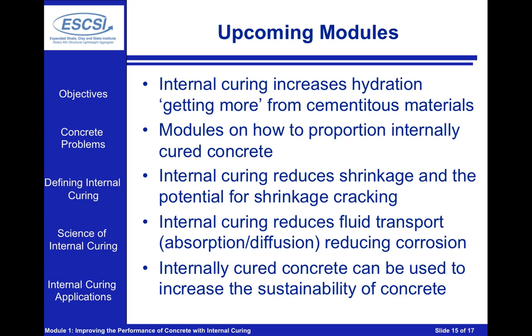We'll also give a few modules where we really discuss the ideas on how we proportion these internally cured concretes and come up with the mixture designs that we're going to use. How do we know how much of the sand to replace with lightweight aggregate? We'll also talk in more detail about how internal curing reduces shrinkage and reduces the potential for shrinkage cracking, and we'll show some calculations that can be done to quantify these effects.